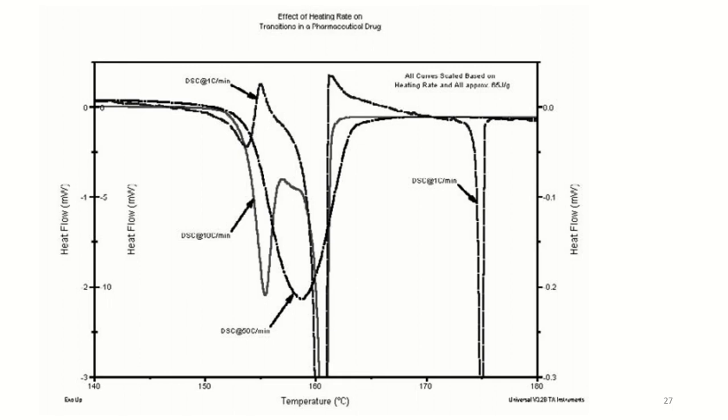The lower resolution signal of conventional differential scanning calorimetry may not be able to detect it even at high heating rates of 50 degrees Celsius per minute, while lower heating rates would not be used due to the sample changing during the experiment.